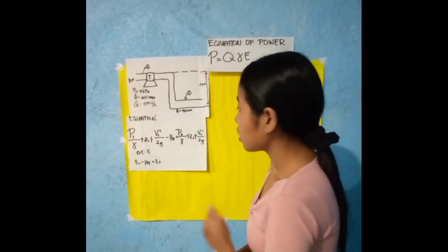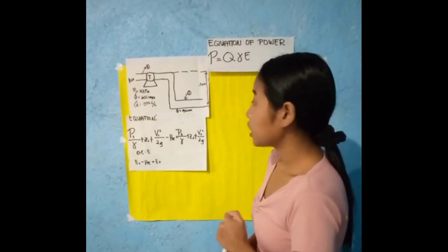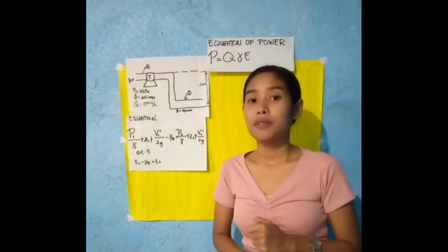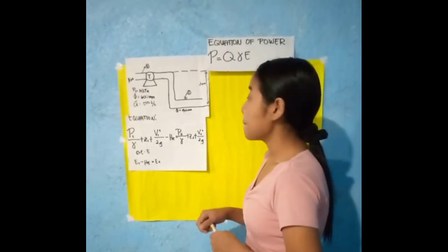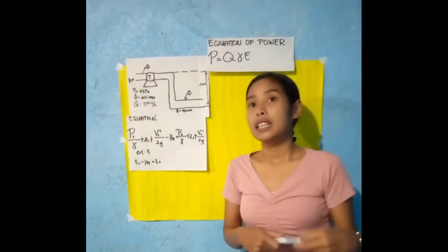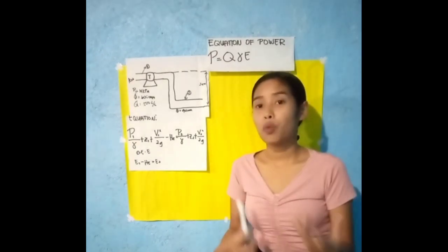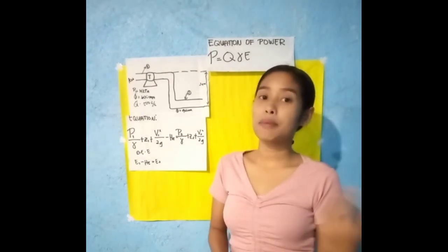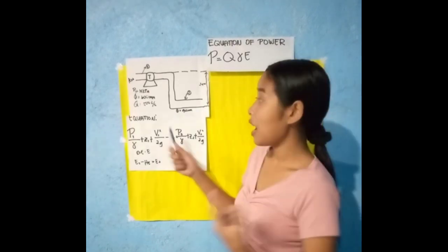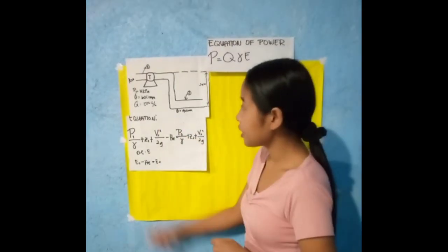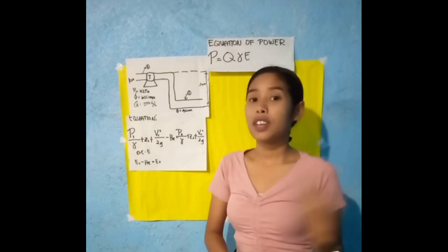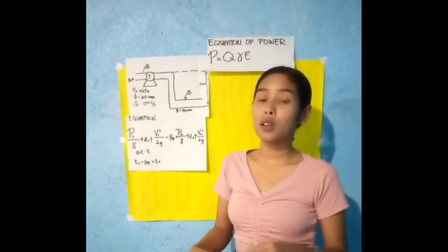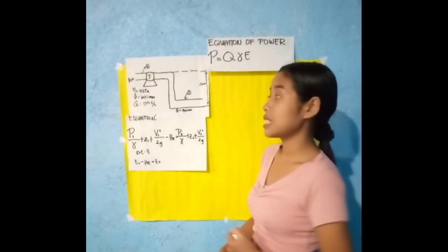So we're going to get our value in velocity. Always remember that the value in point 1 of a volumetric flow rate is the same with the value in point 2. So we have a 500 liter per seconds here in our point 1. Therefore, in our point 2, we have also a 500 liter per seconds.